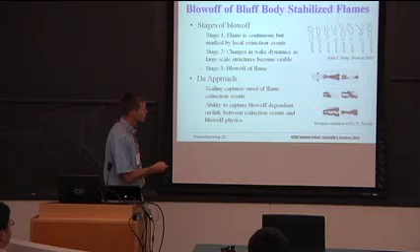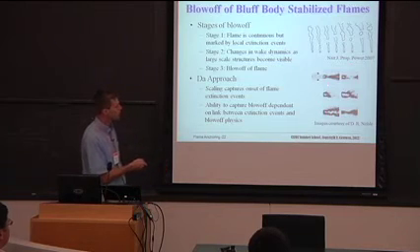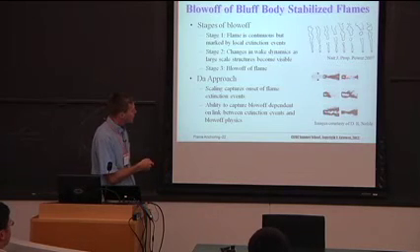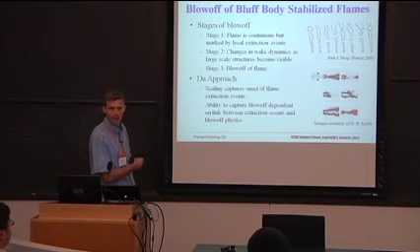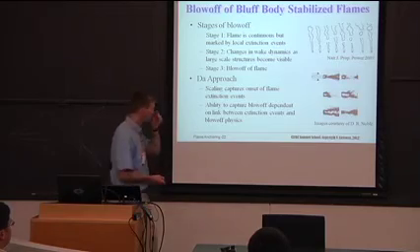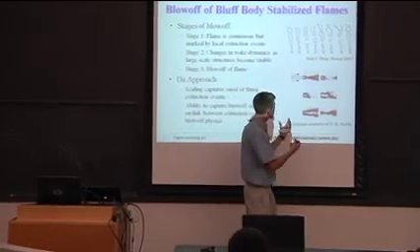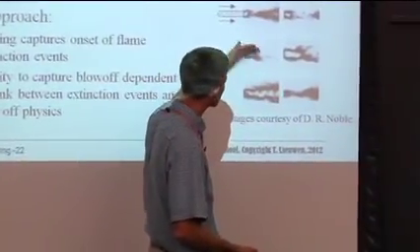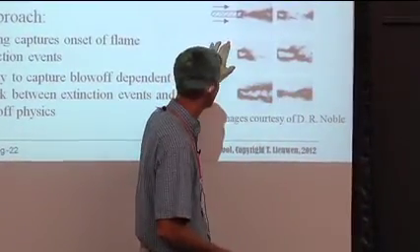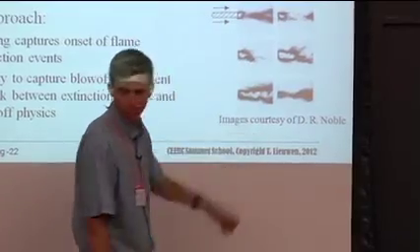Here I actually have some visualizations of the same thing in a bluff body. This is chemiluminescence. You can see extinction, but the flame is always hanging on right in the wake of that bluff body because it's getting piloted. It won't extinguish. But eventually some kind of fluid mechanic event will happen where all of a sudden you don't have hot products in here. Maybe it'll get moved over, pushed downstream, and you only have cold reactants, and that's when the flame lets go.